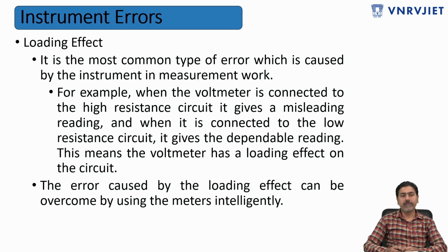And the loading effect is very common when we use measuring devices with the circuit or the instrument where we are measuring the value. Because the measuring device also has some load or resistance that will be added when we connect it to the measuring part. Because of the additional load or unsuitable load connected to the measuring unit, it will give the wrong reading which is not close to the actual value.